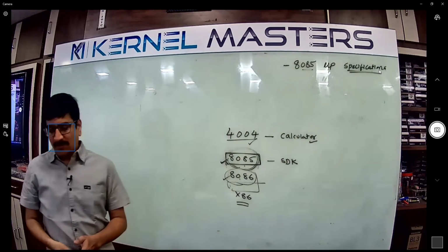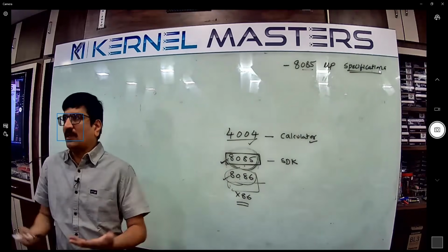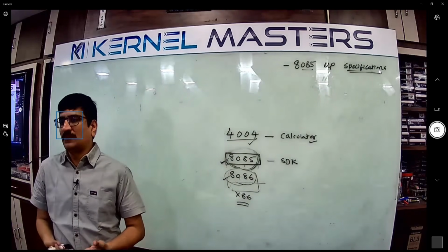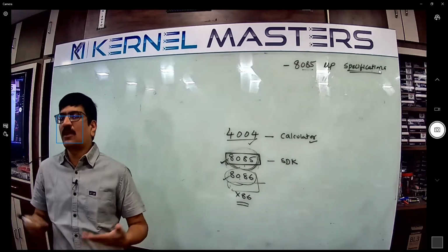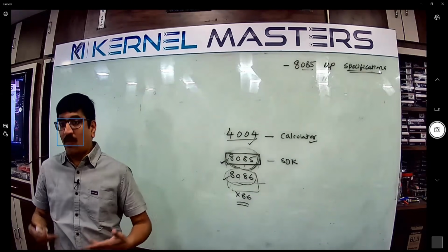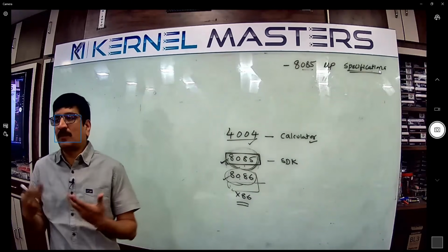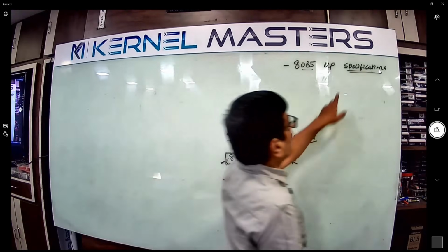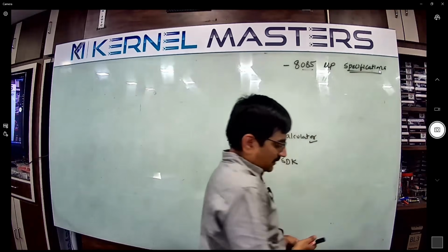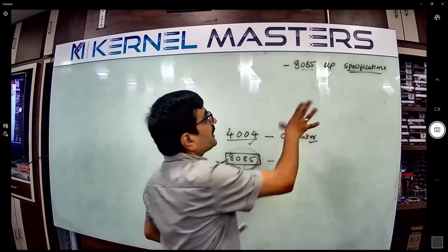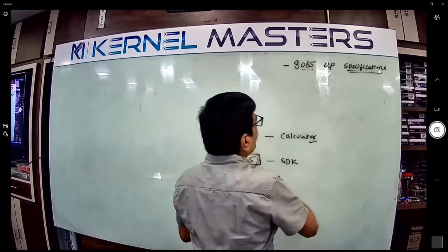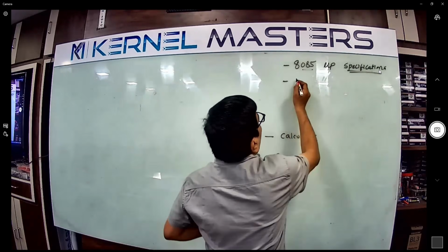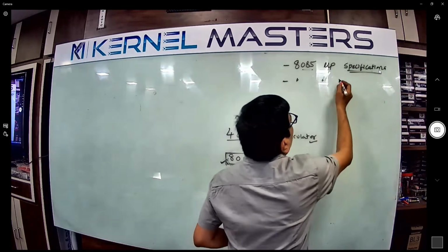The specification is the information: how many address lines, how many data lines, how much clock speed is supported, whether interrupts are supported and what type. It is a high-level summary, the first starting step. Once you understand the specification, then you can go into more detail, with the microprocessor signal description.